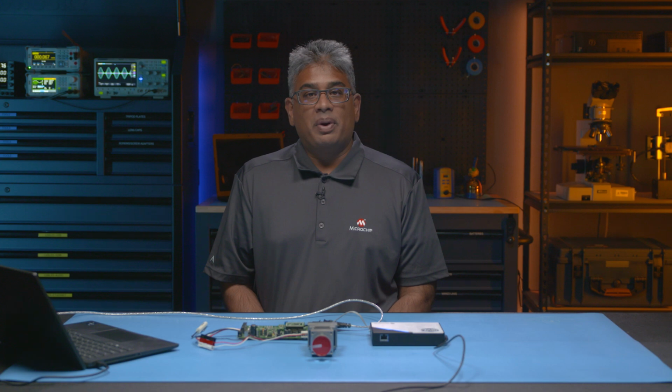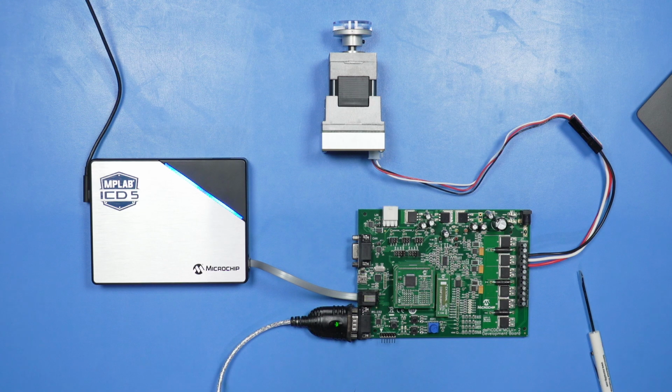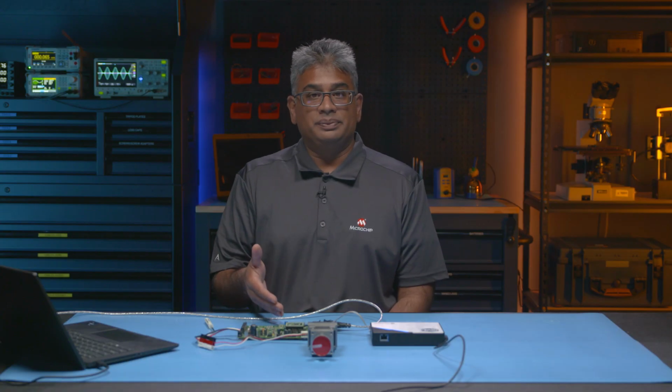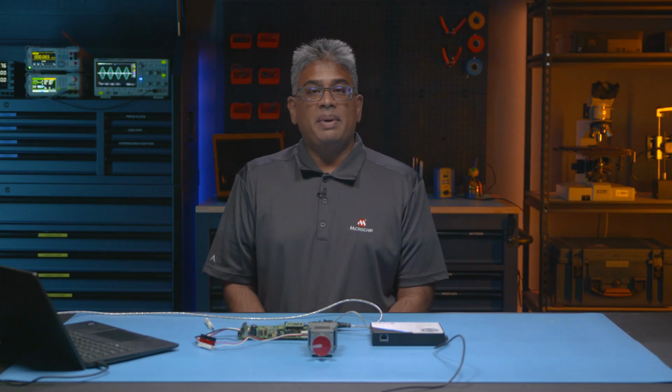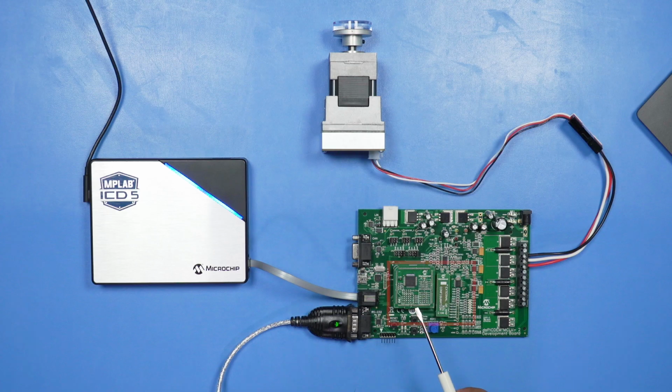Let's talk about motor parameter measurement using motorBench. For motorBench Development Suite version 2.50, the motor parameter measurement is supported using the DSPIC33EP256MC506 external op-amp PIM with the MCLV-2 board, which I have set up here. Before we open the MPLAB X IDE, I'm going to check the setup. I'll check that the PIM and external op-amp configuration board are in place, and they are.